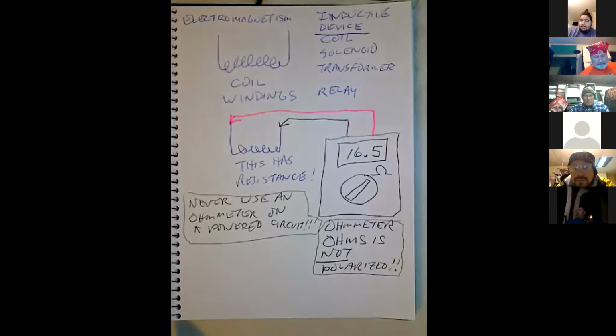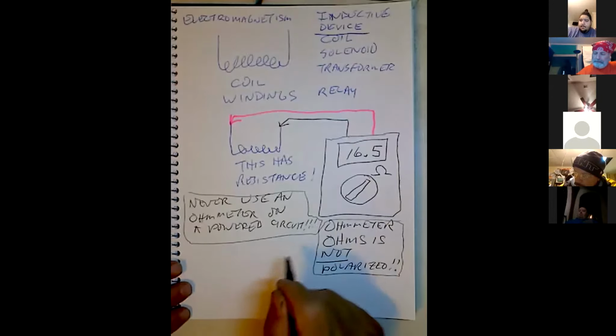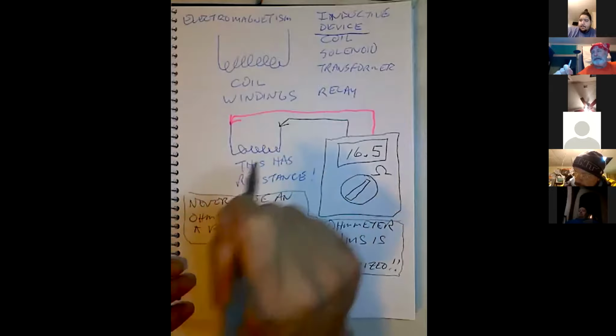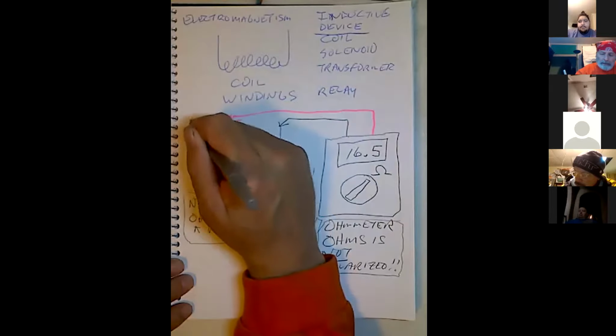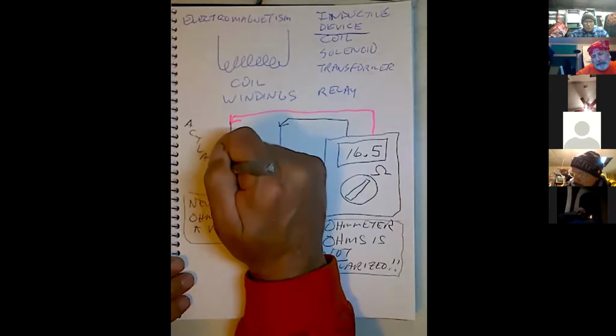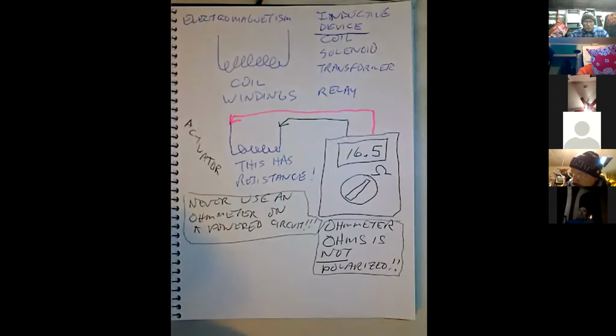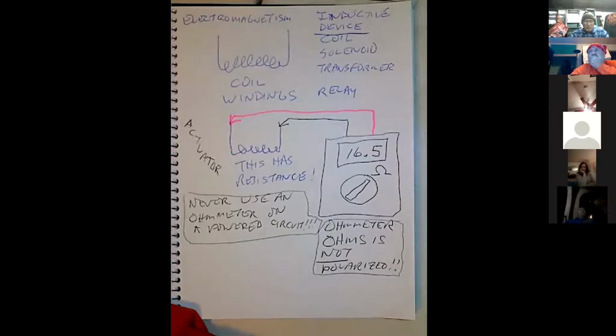Anyways, the point I was trying to make was, 12 volts for motor circuits. Remember, 12 volts is for motor circuits, 5 volts is for information circuits. And this is a motor circuit. This is an actuator, right? Now, what does this report to the computer? Whether it's open or closed? Actuators don't report anything. All they do is do stuff, act, right?